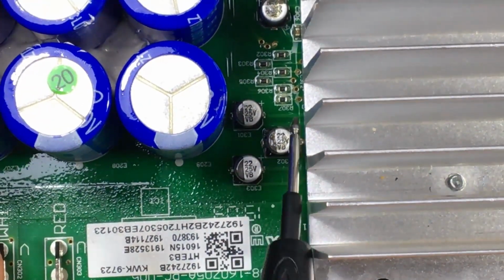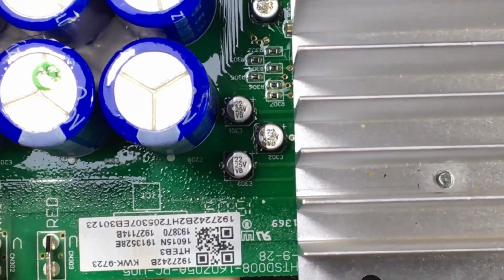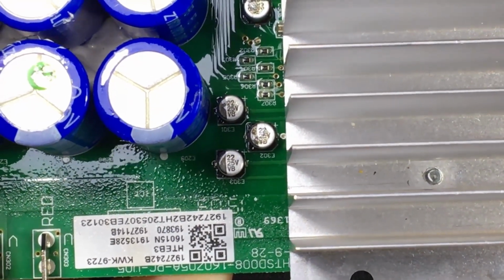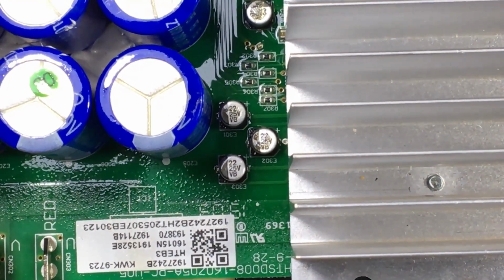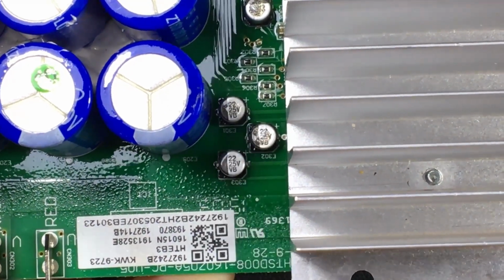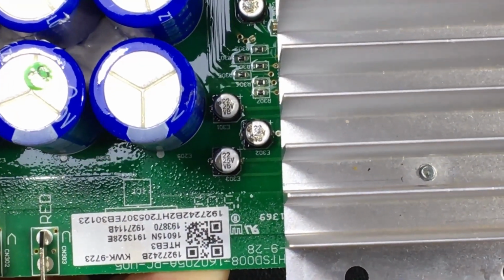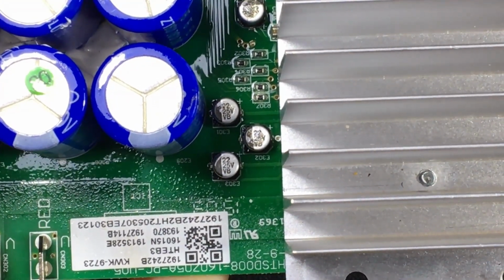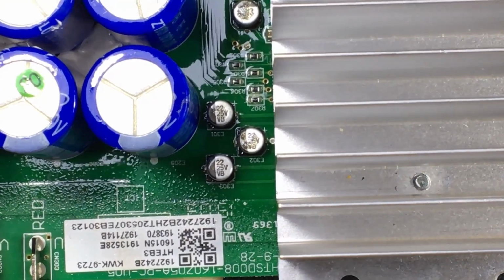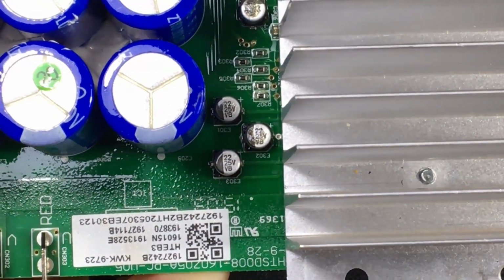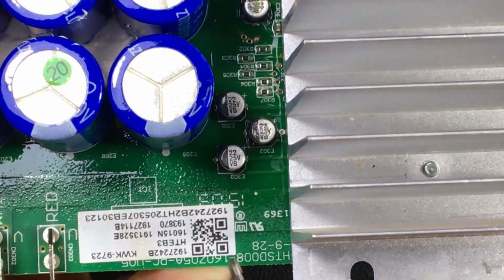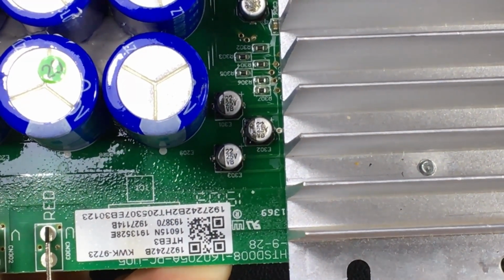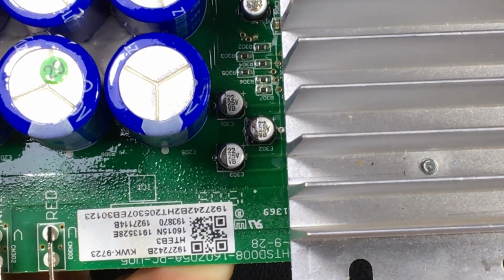An error or deficiency in these capacitors will cause us to have an IPM, motor, or overcurrent error. We will not have an error on the board that tells us the IGBT power capacitors failed. No, this error we will have to deduce ourselves when the problem is in the motor or IPM area. So, if we verify that the IPM is in good condition, we can move on to checking these capacitors, and it may be that we find the problem there.